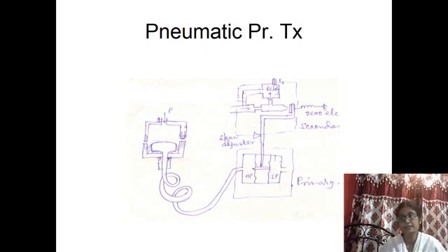That means when the pressure at this side increases, it increases compared with the atmospheric pressure. So pressure increase on the high pressure side means the pressure at this end acts towards the right. So this end will move towards the right, and the motion beam is supported by a pivot, and with respect to this pivot, the upper portion will try to move leftward.